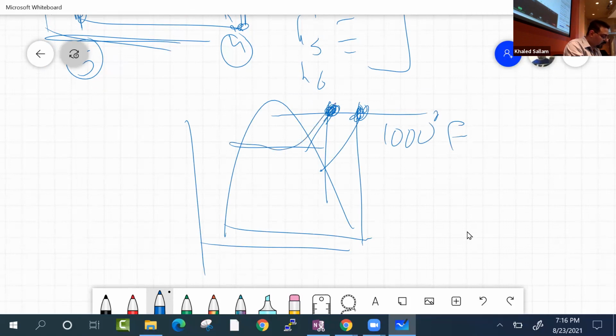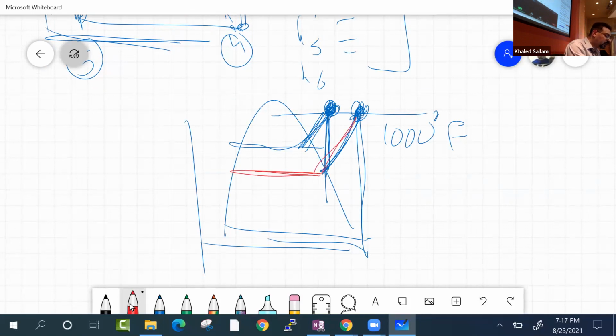So the first time it leaves the boiler and goes to the high pressure turbine, it's capped at 1,000, and then when it reheats, it goes again to 1,000. Right? So in the project, when he was asking you to figure out what is the optimum pressure for reheating, he didn't say what is the temperature that you reheat to.